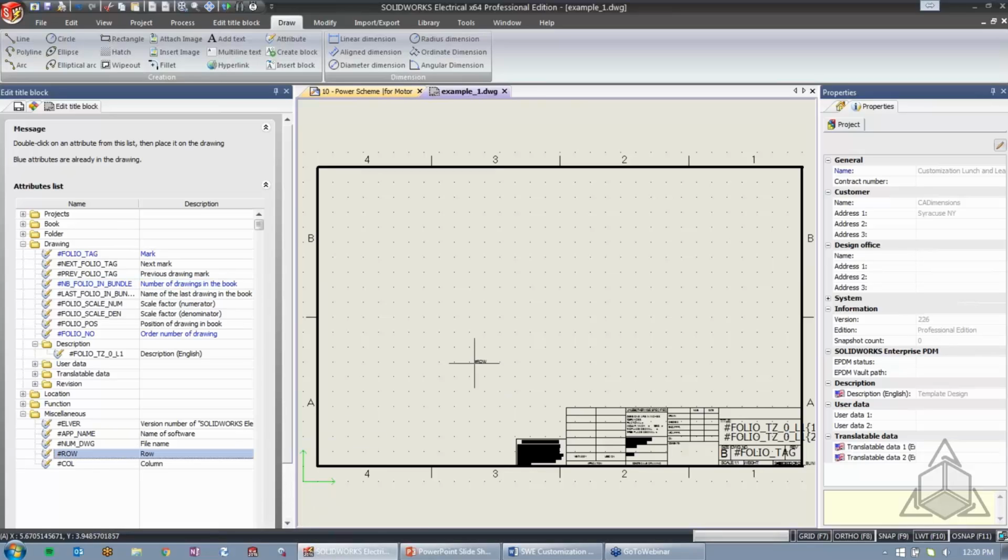and for this one I'm going to turn on my snap setting. So I'll hit F9 to get my snap setting. And in my lower left corner, you can see my actual XY coordinates. So it's on a grid and it's snapping to that grid. So for my XY, I want to place my first row at 1, 10. So over 1, up 10. I'll go ahead and place my first row there.